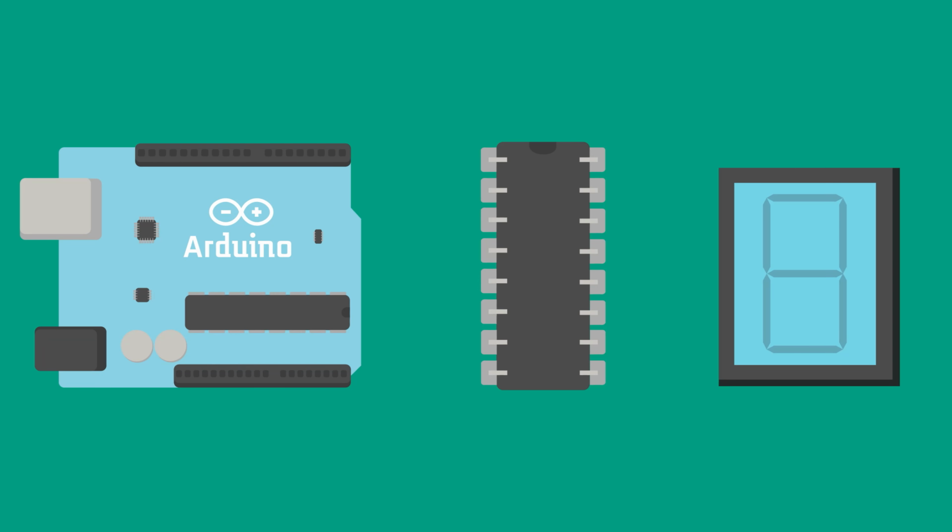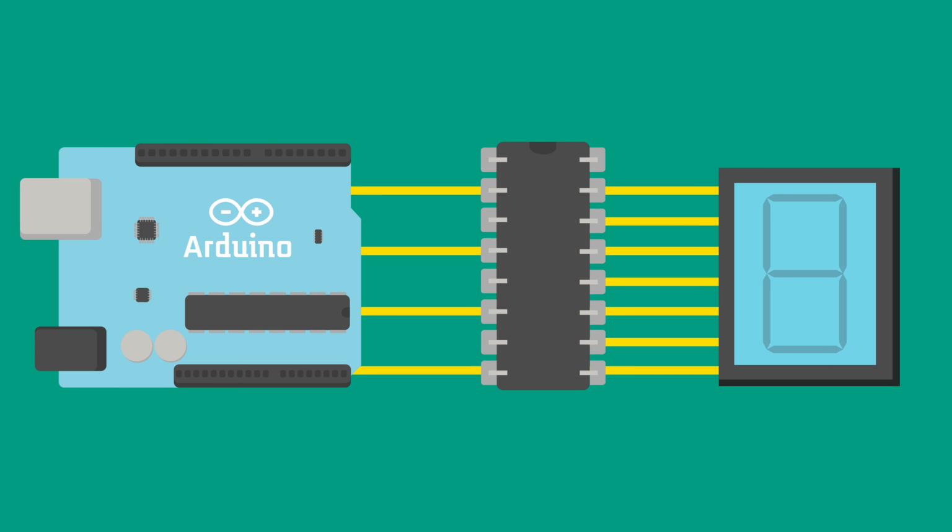This is where the BCD decoder comes in. The BCD decoder can help us in 2 ways: by allowing for easier control of a display and by reducing the amount of pins required. These are the 2 main uses of a BCD decoder, and it is able to do so by converting binary inputs to data or signals that can drive specifically a display. How is that possible? Well, to understand that, we will need to dive into the details of the BCD decoder. Let's have a look.